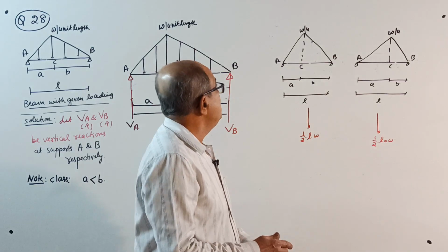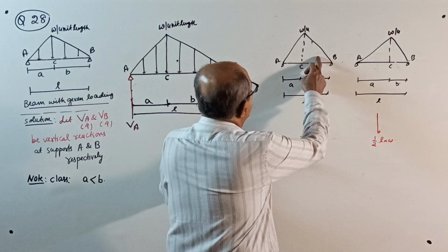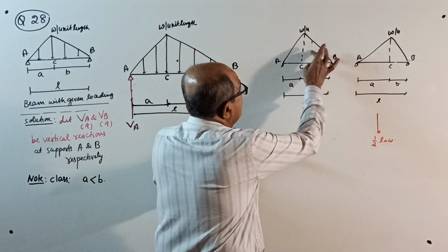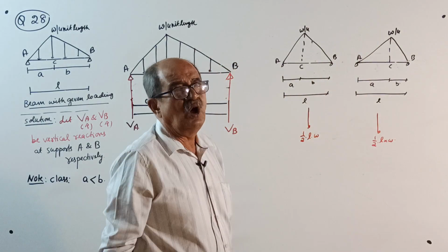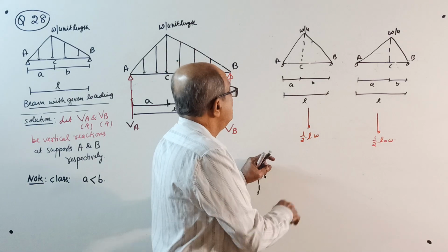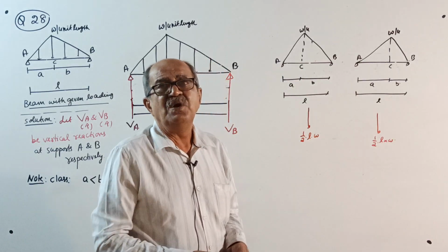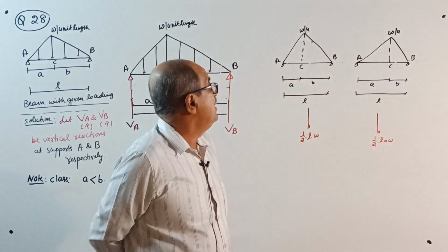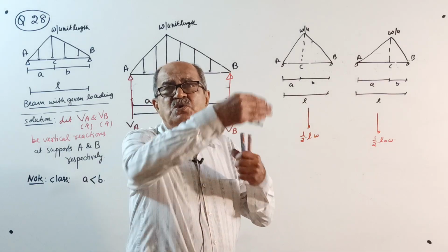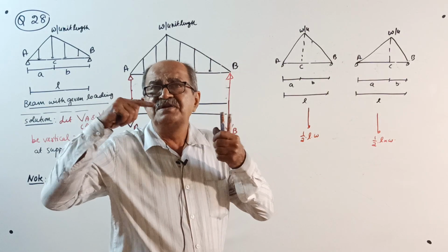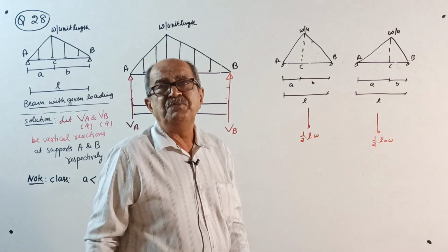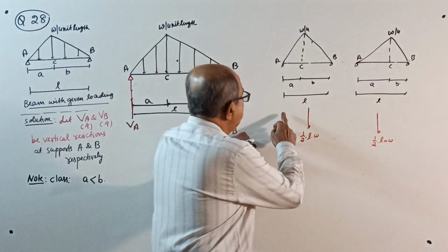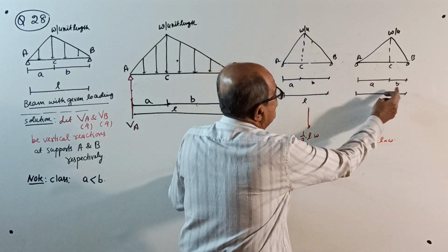Sometimes people, when they get confusion, will take two separate right angle triangles. Okay, done. But for total load it is not required, because that separately you take when you get a moment. When you consider moment, total load into distance of centroid will come. Then confusion comes. So if you want only total load, half into L into W.